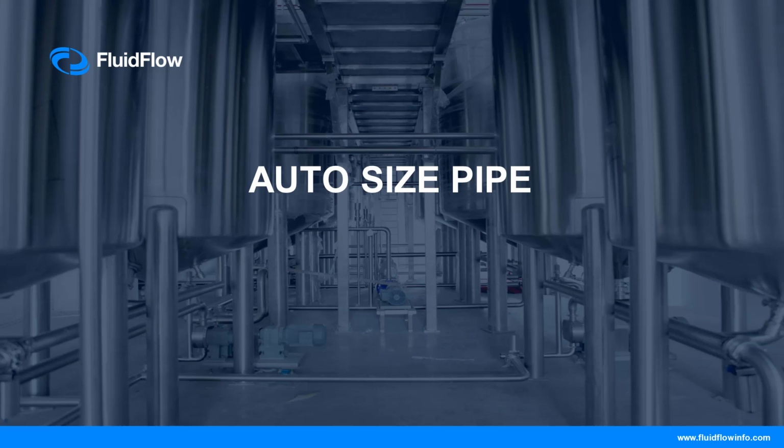Now that we have identified the cause of the warning message in the previous video, we will demonstrate how the velocity in the pipes can be optimized through the use of one of FluidFlow's special features, the automatic pipe sizing. Our objective is to change the size of the pipe to get a better velocity in the pipes.